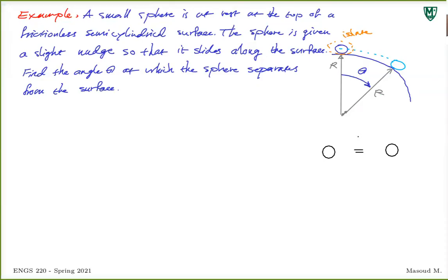Remember, I'm going to draw it where it gets separated, or close to where it gets separated. It's easier to visualize what happens there. It gives me at least a sense of angle. So I'm going to draw it as ER. This is along R, so it's ER. Now remember, perpendicular to ER, increasing theta, that becomes E theta. ER, E theta, right? Left is free body diagram, right is kinetic diagram.